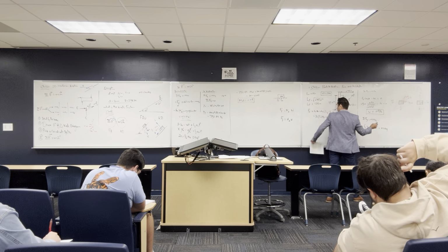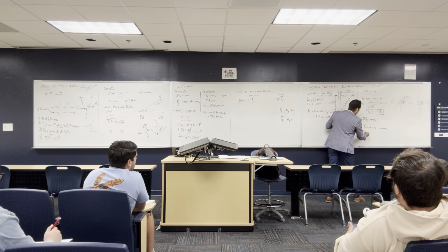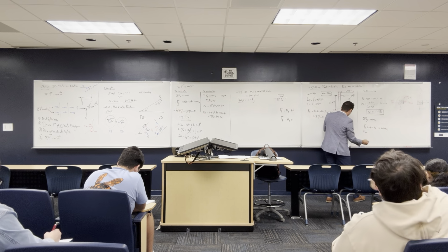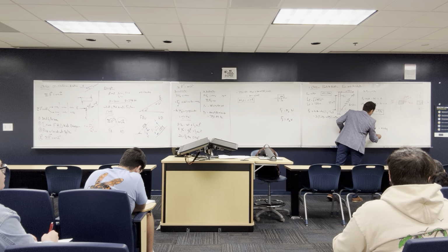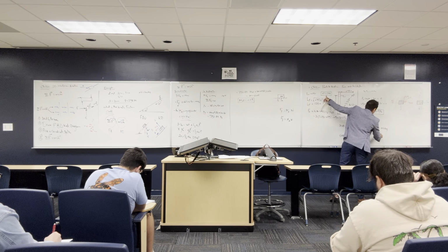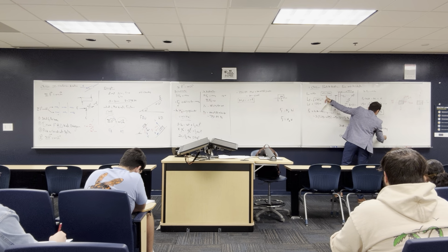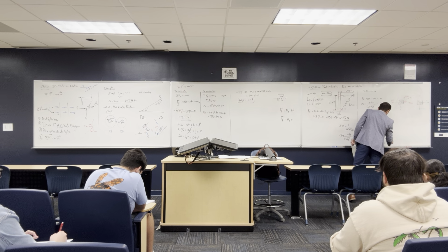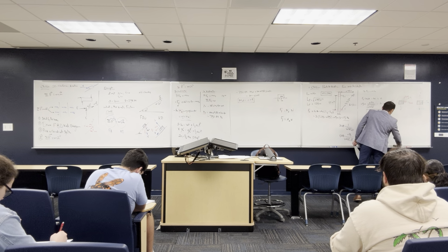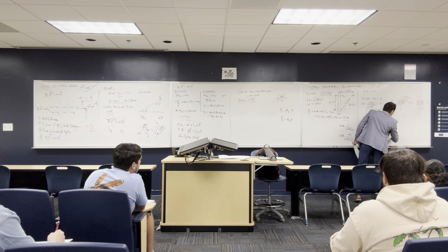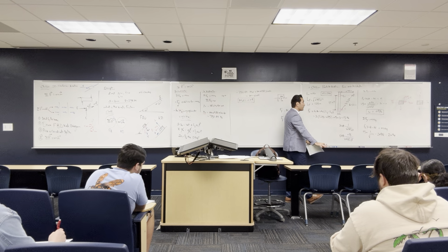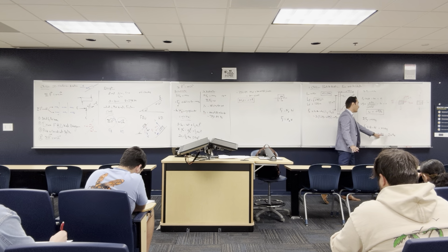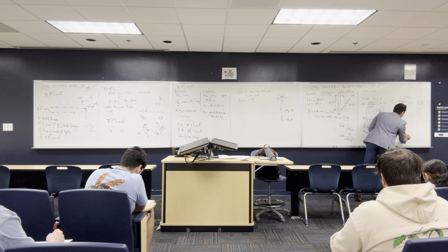So Fs, we calculated, is 1.5 multiplied by sine theta, which is 1 over the root, minus W. For W, I have the mass 2. Never put 2 alone, multiply by 9.81 to convert the mass to weight. And this is going to be equal to the mass, which is 2, multiplied by a_y. And that's it. That's one equation, one variable, which is a_y. And then you are going to find a_y.